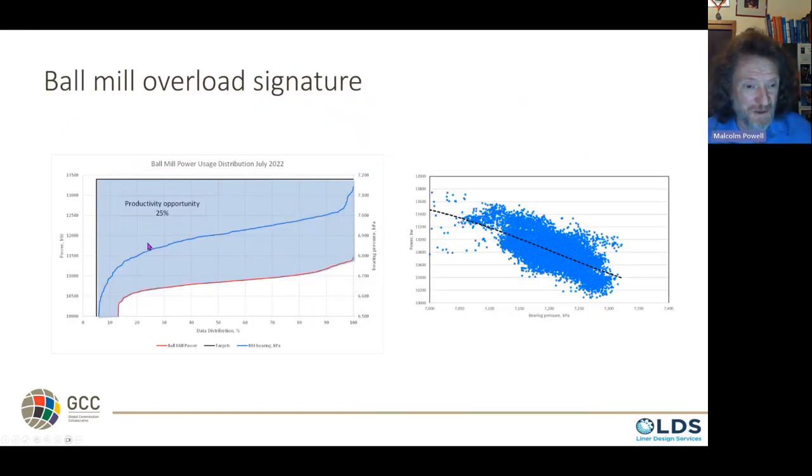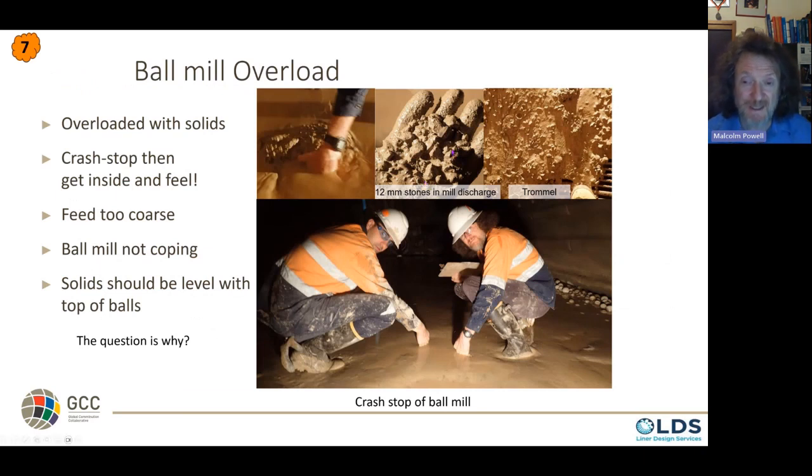So we see this mill, way below where the power should be running, near 1350. They're down here. I'm wondering why. When I look at the power curve, bearing pressure, a proxy for mass, no, bearing pressure is not weight, it's a proxy, and power, as we load up the mill, the power is going down. It shows the mill is overloaded, not with balls, but with rocks. It's overloaded with these rocks, and that's causing the power to drop.